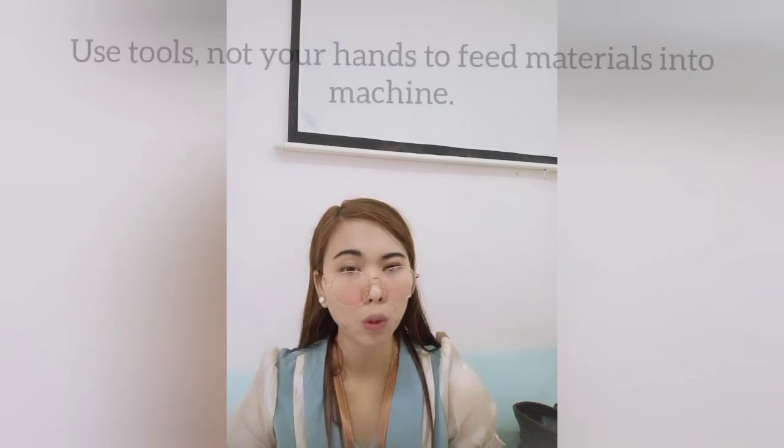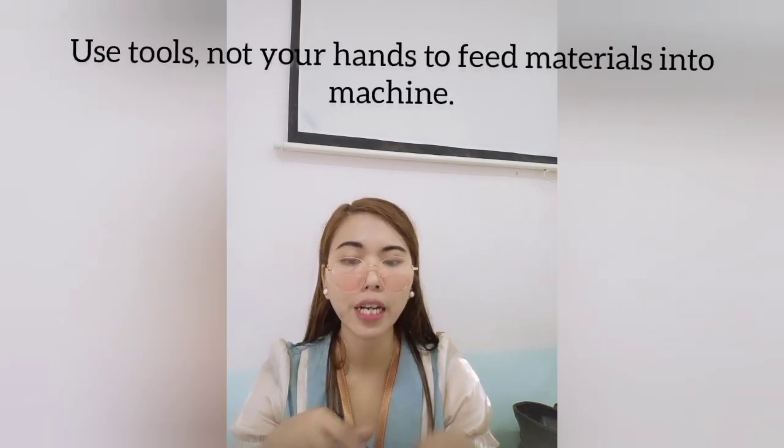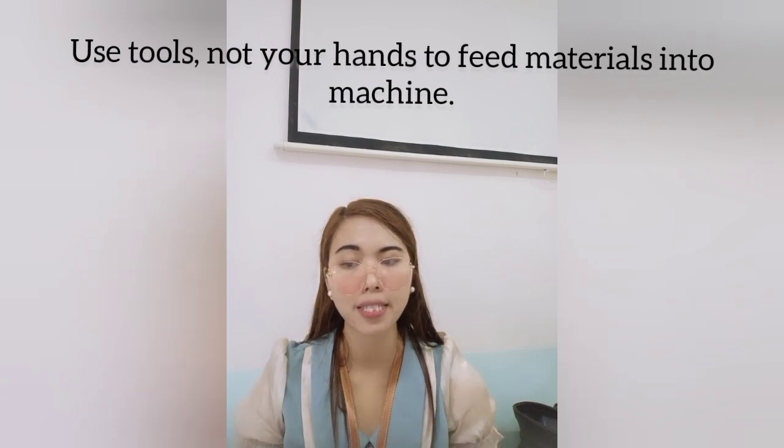And use a tool, not your hands or your fingernails, to feed materials into machines. That should not be done. Of course, don't forget, you need to wear your assigned PPE. And do not try to operate machinery when you are under the influence of alcohol, and also drugs that are prescribed for medications.